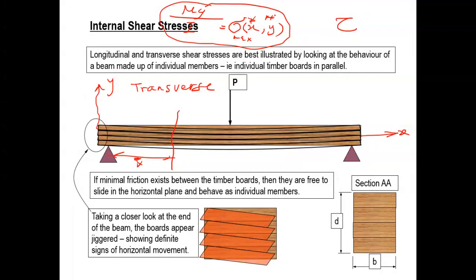We are looking for x star, y star. How do you find x star? You plot the bending moment diagram. By looking at it, you find the maximum is there. But how do you find y star? You have to imagine this is the section. I find the neutral plane, and then this is a judgment. Is this one larger or this one larger? Whichever is larger, that would be the y star.